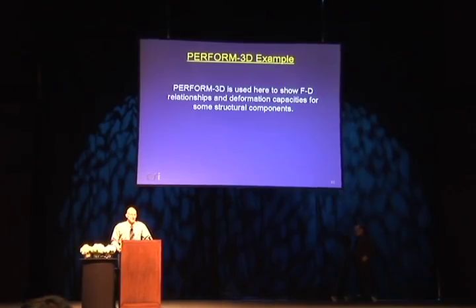When you're building a model, most of your time is actually going to be spent in that component properties portion of the input. Defining the geometry is relatively simple. Defining the nonlinear component properties is far from simple. In a linear analysis, it is a simple process. You just give it material properties, you're done. Elastic modulus, maybe a Poisson's ratio, that's it. Nonlinear, no way, you've just begun. That's the beginning.